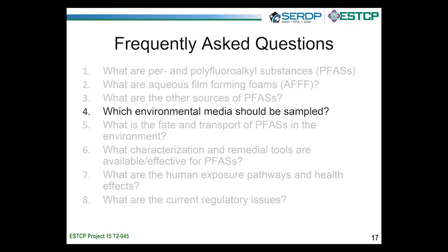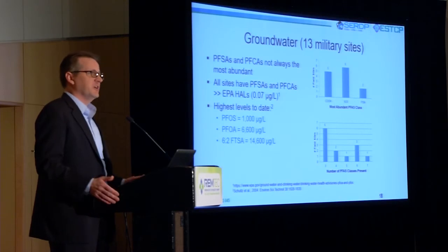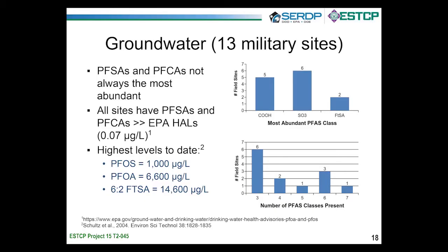Great, well thank you, Jennifer. So I'm going to now address the question of if you're looking at a contaminated site or a site potentially contaminated by these PFASs, what media should be sampled? It's not going to come as a surprise that I'll start off talking about groundwater, particularly at these AFFF impacted sites. And what we're showing here in this slide is a compilation of data primarily coming from Dr. Field's lab, where we've looked at various sites that have been impacted by these aqueous film forming foams and looked at the abundance of these various compounds in the groundwater.